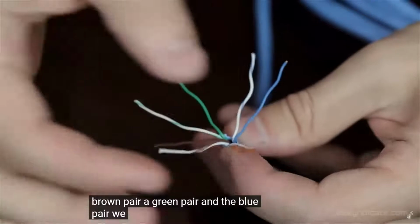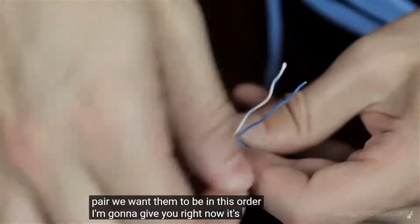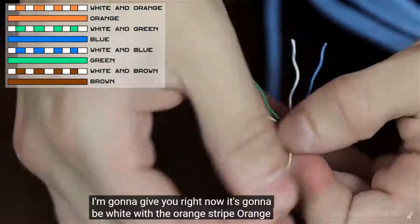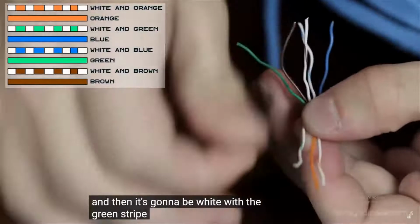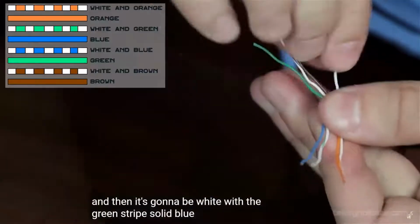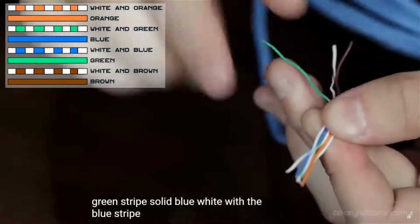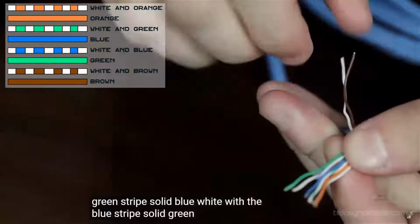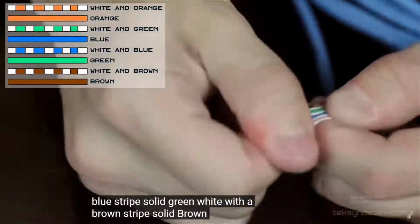We want them to be in this order I'm going to give you right now. It's going to be white with the orange stripe, orange. And then it's going to be white with the green stripe, solid blue, white with the blue stripe, solid green, white with the brown stripe, solid brown.